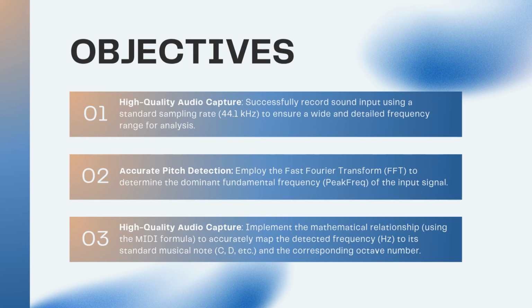Objective 3: implement musical mapping. The final step is translation. We had to implement the precise mathematical relationship, specifically using the MIDI formula, to accurately map the detected frequency in Hertz to its standard musical note, C, D, etc., and its corresponding octave number.